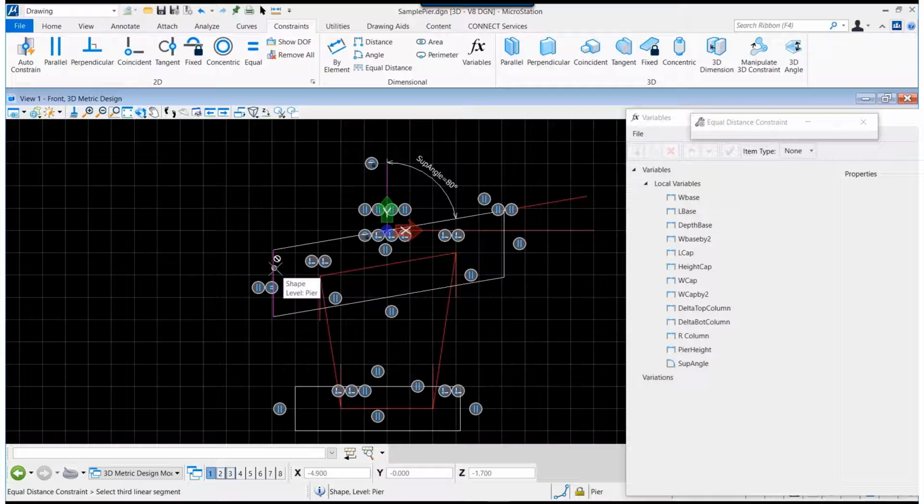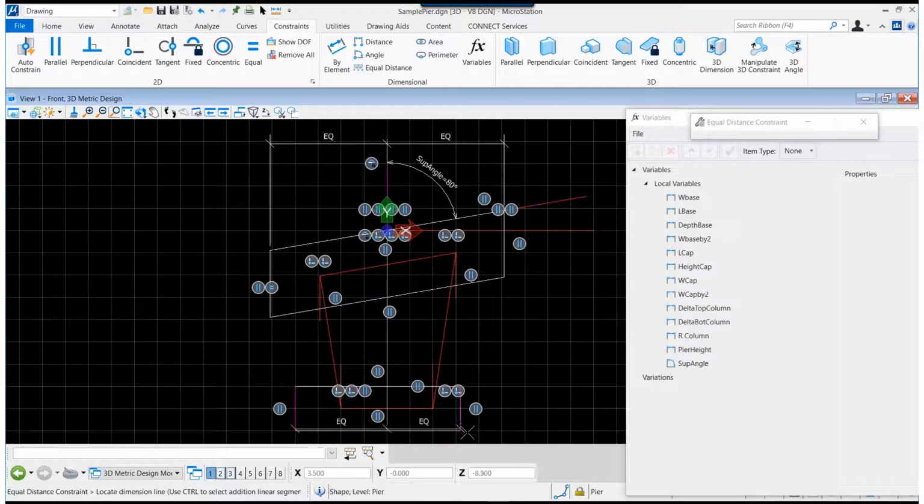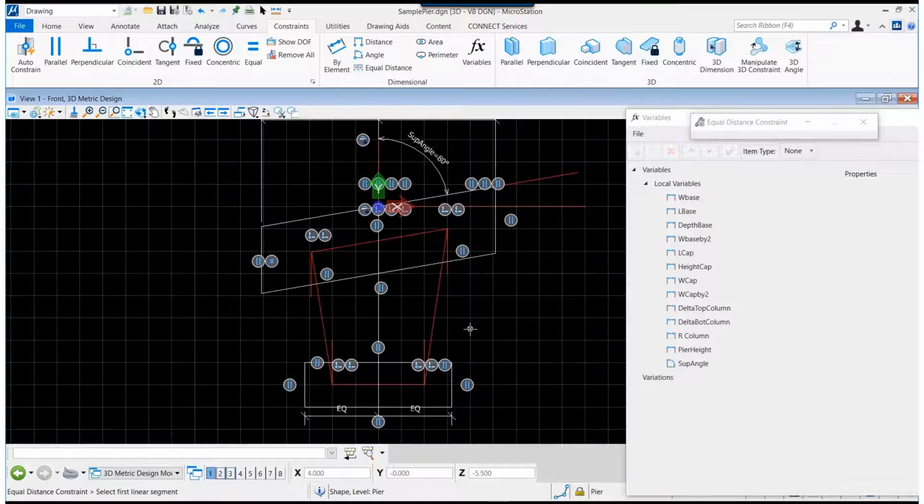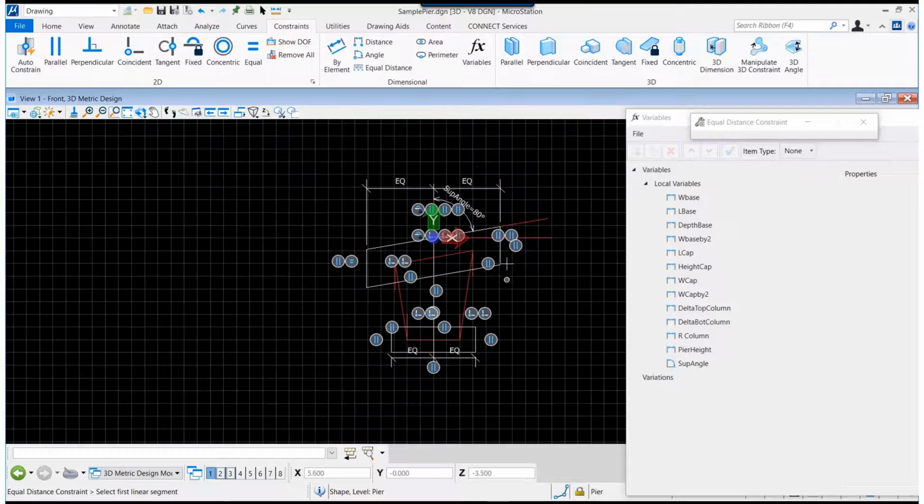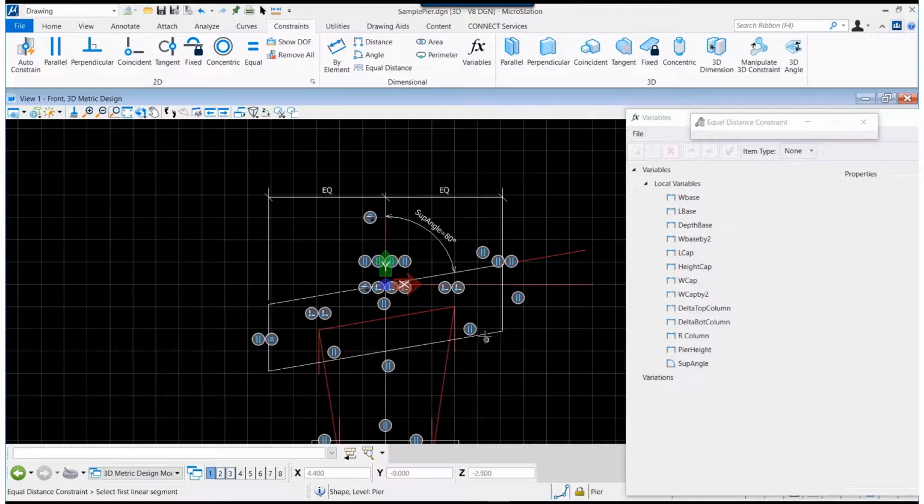And then also not only the behavior of the element, but also the distance that you're going to use. So there are not only constraints on connections, right, perpendicular, parallel, coincident, but also restrictions on distances. So you can put what are called dimensional constraints. So these have to be the same distance as the other. This has to be, well, not the area, but I would say mostly distance and angle, especially when you're doing superelevation, right? So one distance will become equal to the other, and so on and so forth.